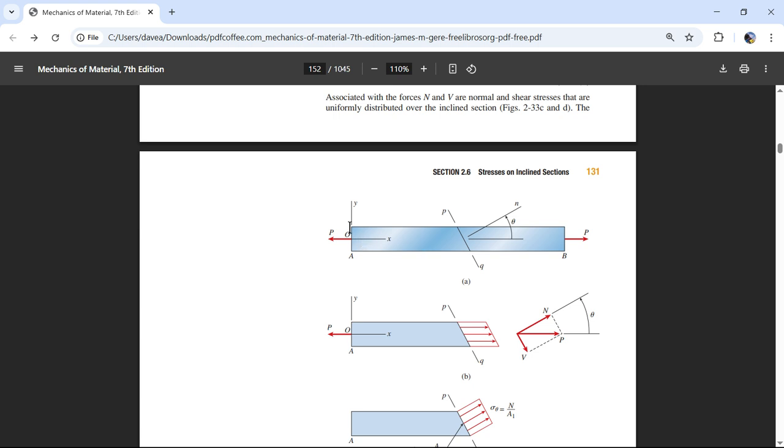And you can see that by taking the steepest cut possible. Let's take a cut from this corner all the way to this corner. And I think that is a very good representation of what happens along that cut. You can imagine if you got a chunk of wood and you make a cut like this, and then just take double-sided tape and stick those two chunks of wood together and start pulling on them. Well, hey, it'll probably fail along that double-sided tape.